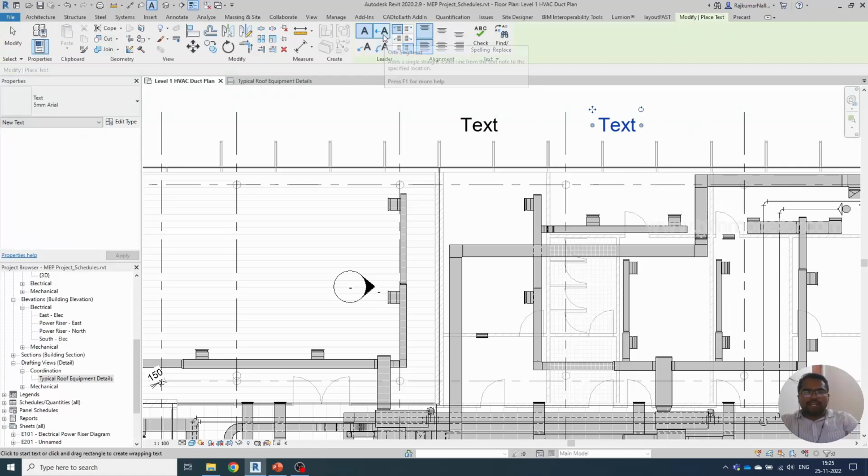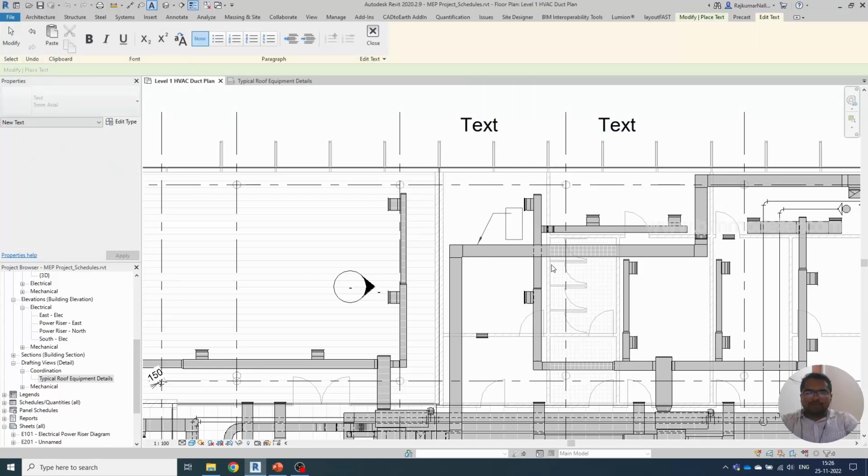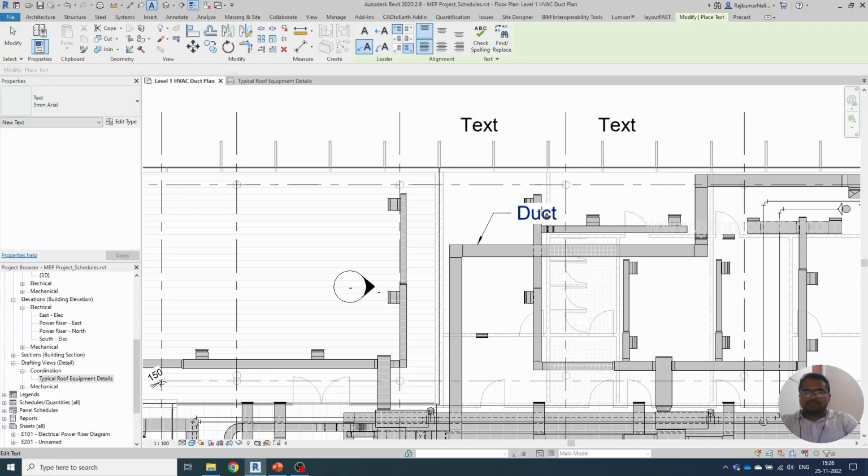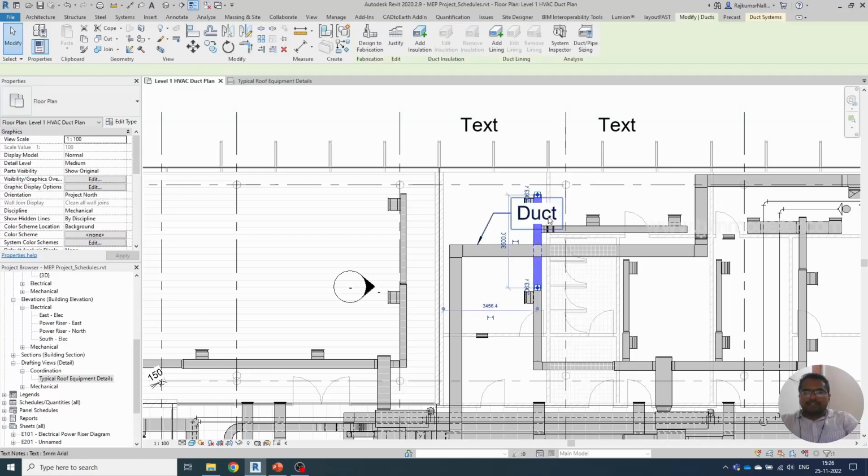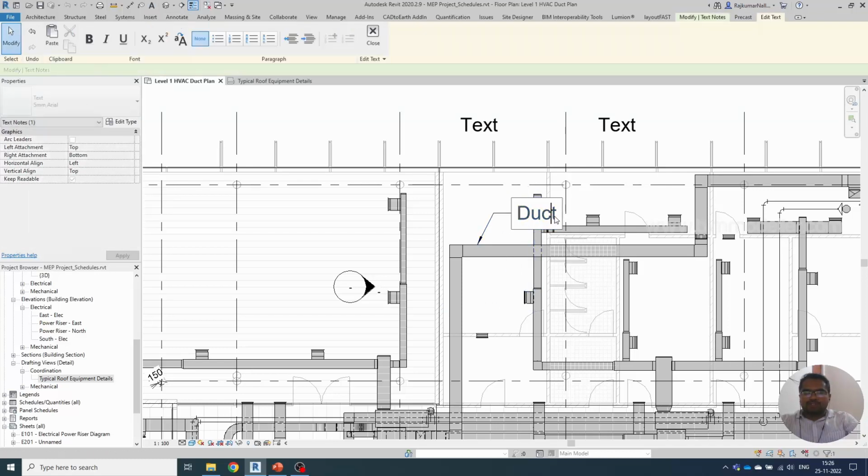You'll be able to use the arrows, these multiple options with the arc and without bends and with the 2-point arcs like this, and you'll be able to type that duct like this. And we can give notes, the text will be used for notes, so we can say that duct must be small in size.